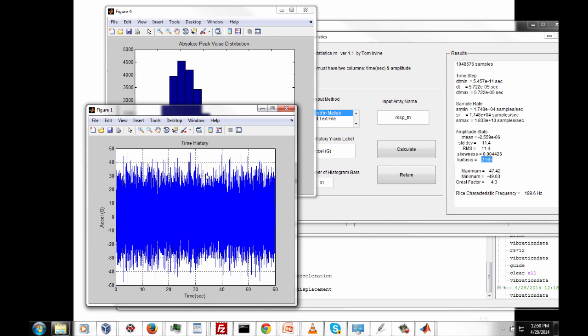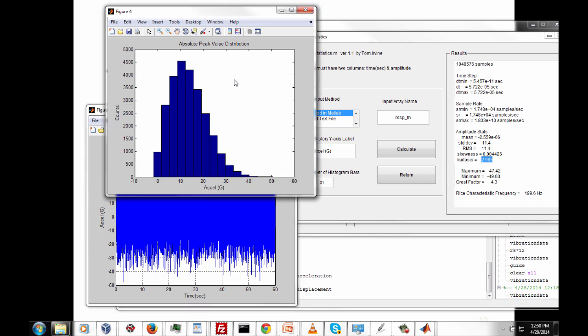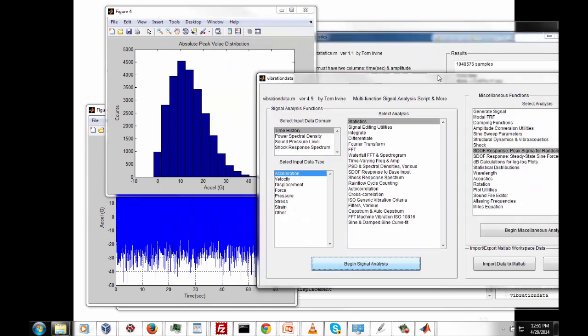We're going to reduce this time history so we're only retaining the local peaks, whether they be positive or negative. So we're going to take all our localized peaks in a sort of subset time history, and we're going to take a distribution, a histogram of that subset, and it's going to be what we call a Rayleigh distribution.